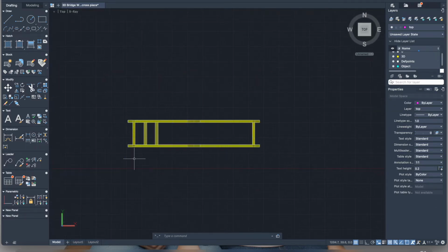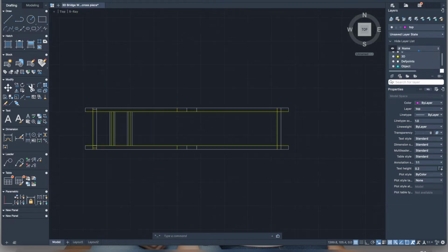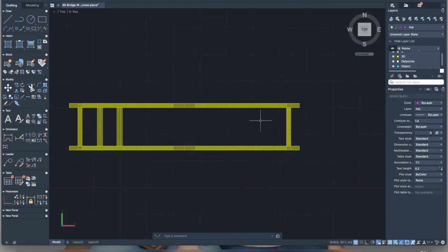Now you might be tempted to work right in here and create a box and put your X's here. But one thing that will happen is because this is raised up and your lines are snapping to the edges, you will end up creating a structure that's on different levels. So if you were to rotate, you'd have some lines up and some lines down and nothing would actually be connected. So you don't want to do that.